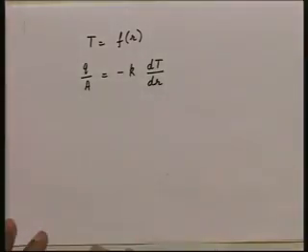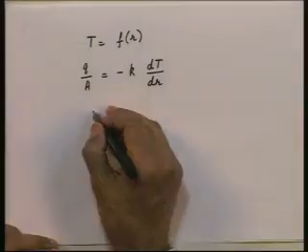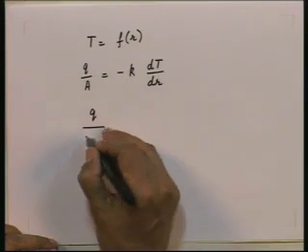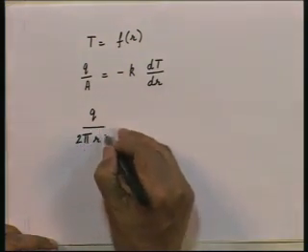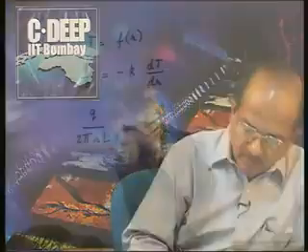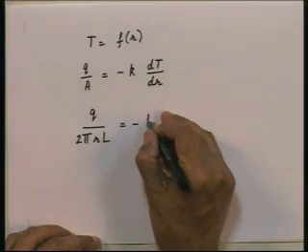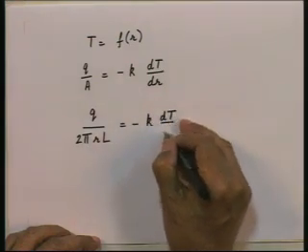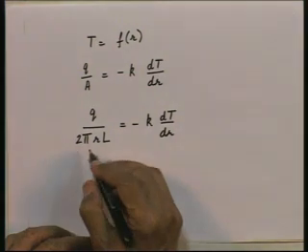And now, mind you, in a cylindrical situation, the area A across which heat is flowing is continuously increasing as we move outwards in the radial direction, unlike the infinite slab case. All right, you follow that. Therefore, for A, I will have to put 2 pi r L, where r is any radius within the cylinder, L is some length of the cylinder. Q divided by 2 pi r L is equal to minus k dT/dr. And Q is a constant, of course.